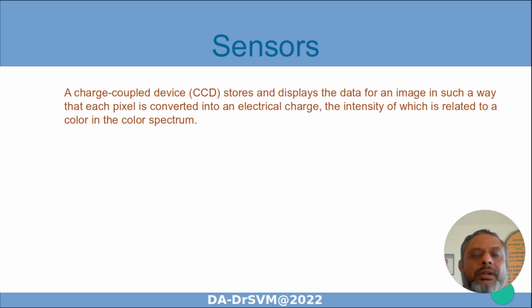So we have basically three types of CCD. One is more tuned towards red. So this charge accumulation is more active in red light, one more active in the green light, one more active in the blue light. So three together can form one RGB. So the three data together can represent any color shade of the visible spectrum.